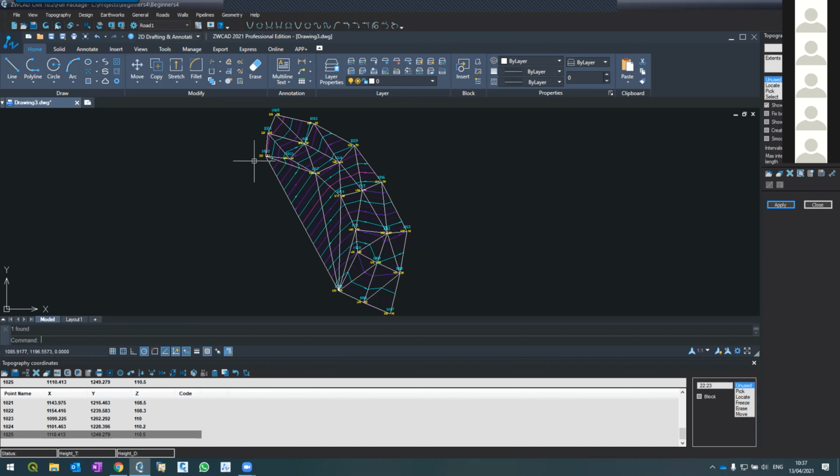So again, the problem of the borders is where our surveyed area is not convex. It has a road, it goes like this. And the software automatically interpolates to the maximum coverage area. Although we know that the contour lines end up here, the software continues with additional triangles, which we don't want. So this is the border problem.